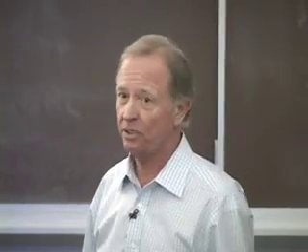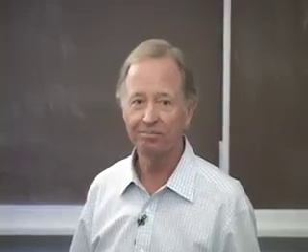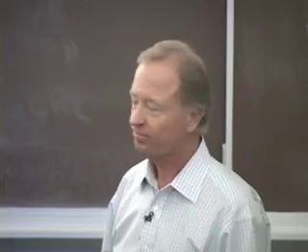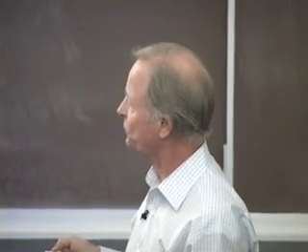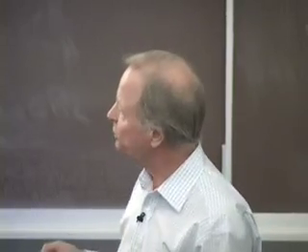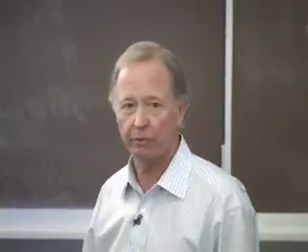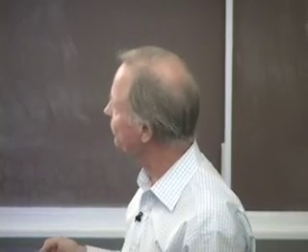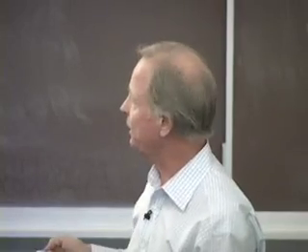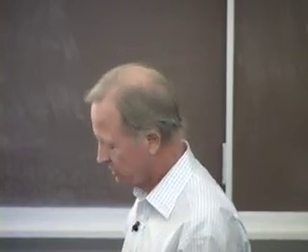And you might say, that's pretty contrived. You're absolutely right. And so there's no denying that. And you've probably never used G sub c. You've probably never really thought this through, because you just merely put a pound here and a pound there. But really what you should be putting here is a pound sub F for pound force and a pound sub M for pound mass when you use this, and stick in this G sub c, this gravitational constant.